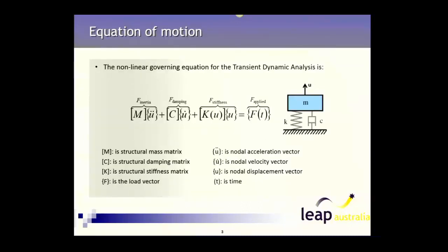Okay, so with a full transient or a dynamic analysis, we basically solve the full equation of motion. So it means we include any time-dependent effects of any applied forces. So our stiffness can change, it can be non-linear, and then we also include damping effects and also our inertia effects. So you can calculate the motions of bodies by using a full transient simulation.